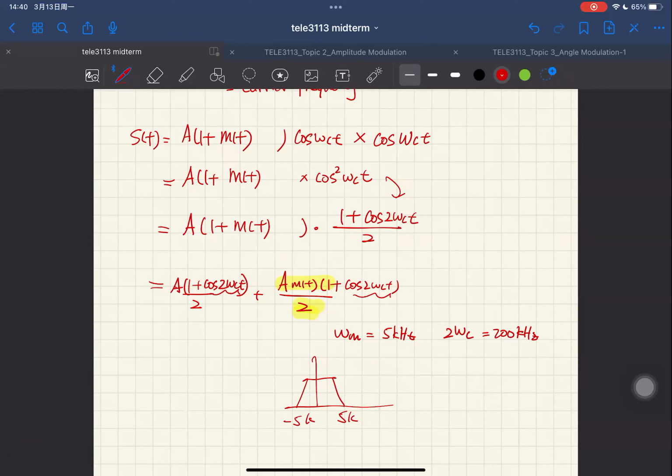We do multiplication, we do a trig identity, and then we can realize that the expansion involves different frequency components. Essentially we just pass the signals through a low pass filter, and we can get rid of the component that we do not want, and keep our message component and reform it. So that's the trick we're going to use throughout the course.